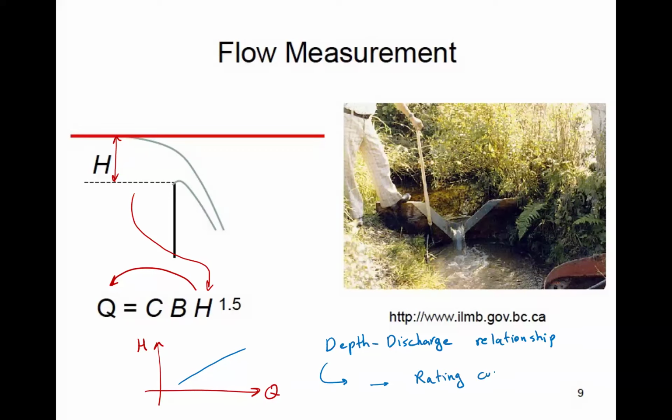So when you hear them say, oh, the rating curve for this station, this river, at this place is this graph, that's what it means. It means for different water levels, you can convert it to discharge. Measurements have been done and calibrated, so we have this measurement available.